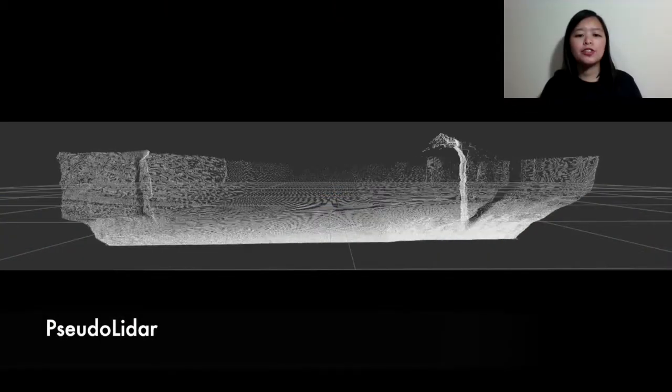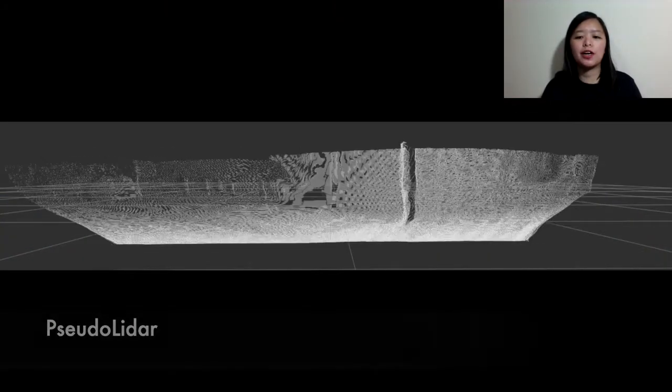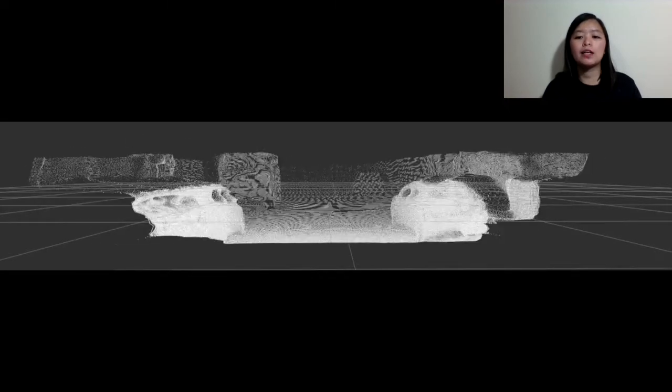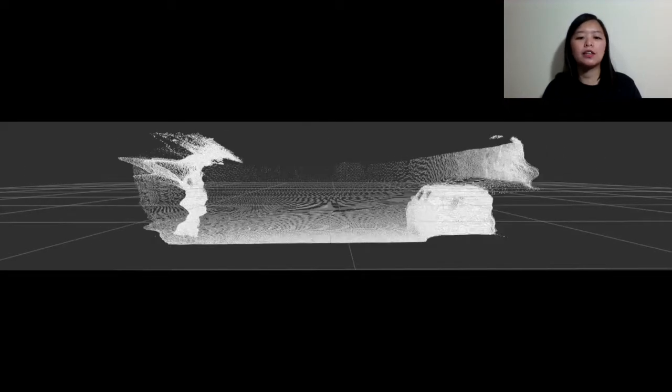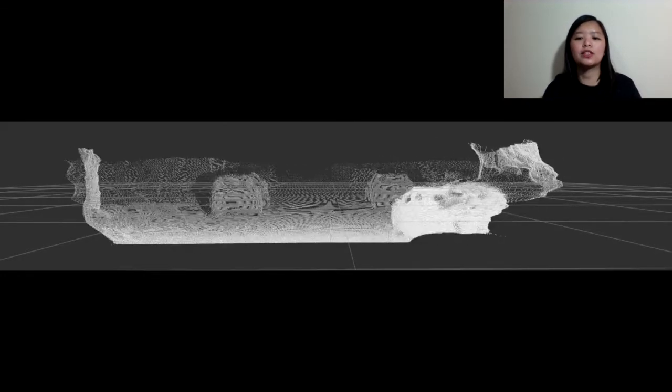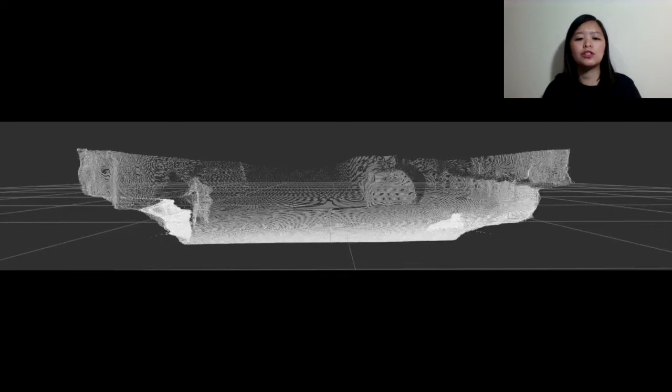The second approach used an open source depth estimation algorithm named BTS and experimented with projecting the depth map back into a 3D point cloud using a method called pseudo-lidar. This aids in creating dense point clouds for object detection algorithms and further reduces the need for a lidar.